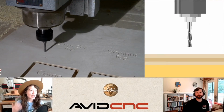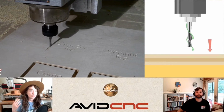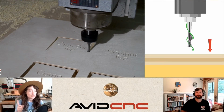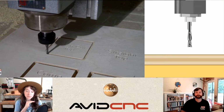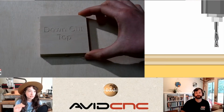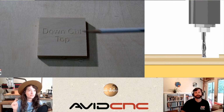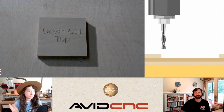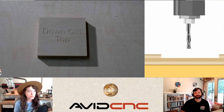So down spiral, I really like to reach for this when I am working with plywood and hardwoods or softwoods, especially for doing pocket machining. When I want a really nice bottom surface finish, as well as preserving the top veneer of my material, down spiral is really great for that. I don't tend to reach for this when I'm doing a through cut, however, and that brings us to compression bit.